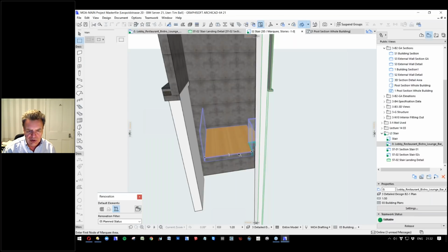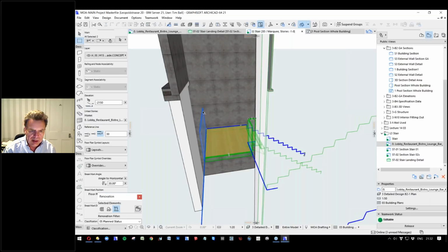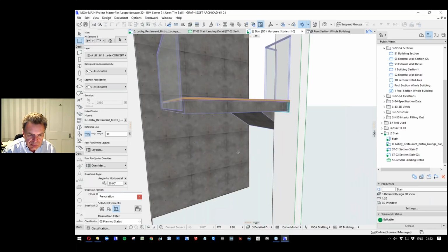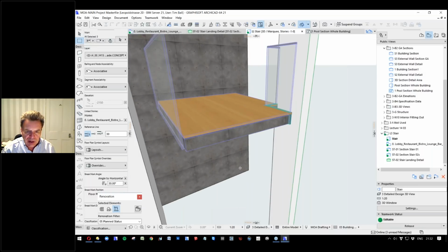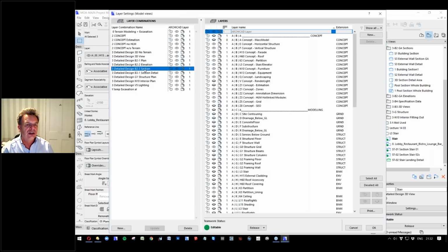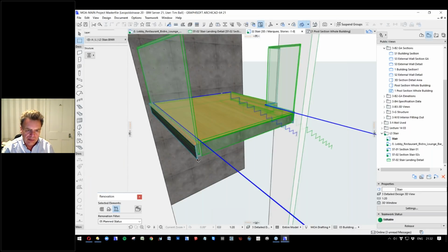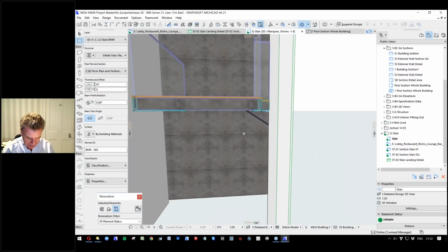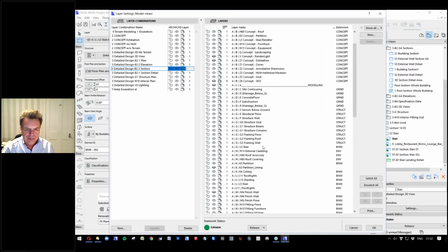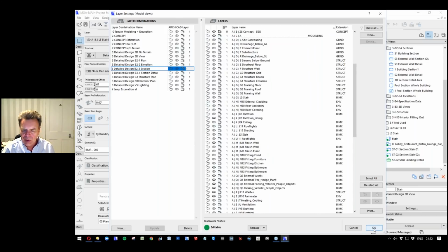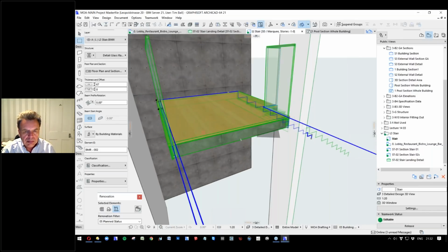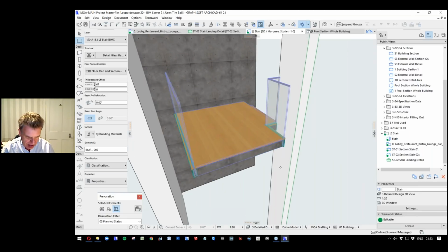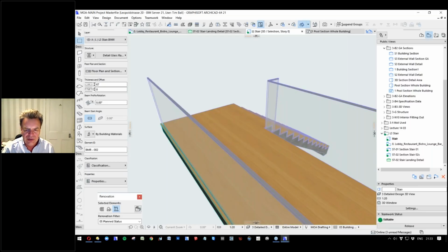So let's actually, if we now just pick the stair and that, and that. Oh, there's a few things aren't turned on, some layers aren't turned on. Let's change to the section. There we go, so we've got that. And also, we haven't got our stair on. Yeah, we should have. Anyway, it gets as close to what we think. And if you then think, well, I only want those, if you hit F5 again, it just identifies that bit.